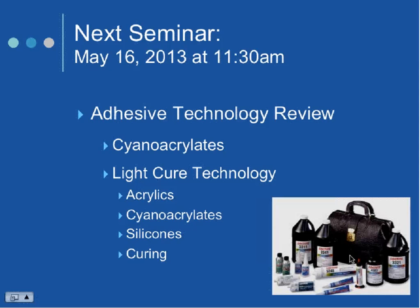If you can get a handle on your forecast and maybe do a buy spec, that's another thing I haven't mentioned, but a buy spec is an excellent way to manage that. It's a buy specification where you write down, I want your product to meet XYZ, maybe a viscosity, tack-free time, some things right off the TDS. Then you might also put a clause that we would like the product to have a minimum of 9 months use-by date, shelf life. I think 9 months is about the most you can expect, because you have to allow for some transit and sitting on a distributor shelf.